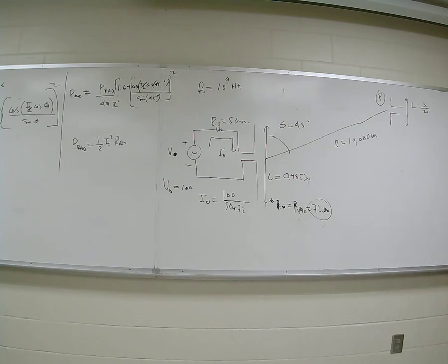I'm going to stop for a second. Okay? Not quite done. Y'all agree we can get E and we can get average power? Show of hands. I'm not going to give you the gain of a short dipole. The short dipole is what? 1.5 sine squared of theta, correct, class? I'm going to give you the half-wave dipole. And the short dipole and the small loop have the same exact directivity. Don't they, class? With me?